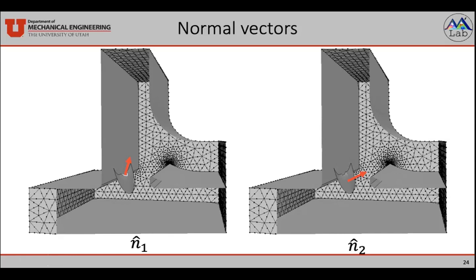And N2 shows that as the crack grows downward, N2 now points more to the right. So many of these models had a large enough difference between the initial crack orientation and this crack growth path that we deemed it necessary to include in our symbolic regression model.